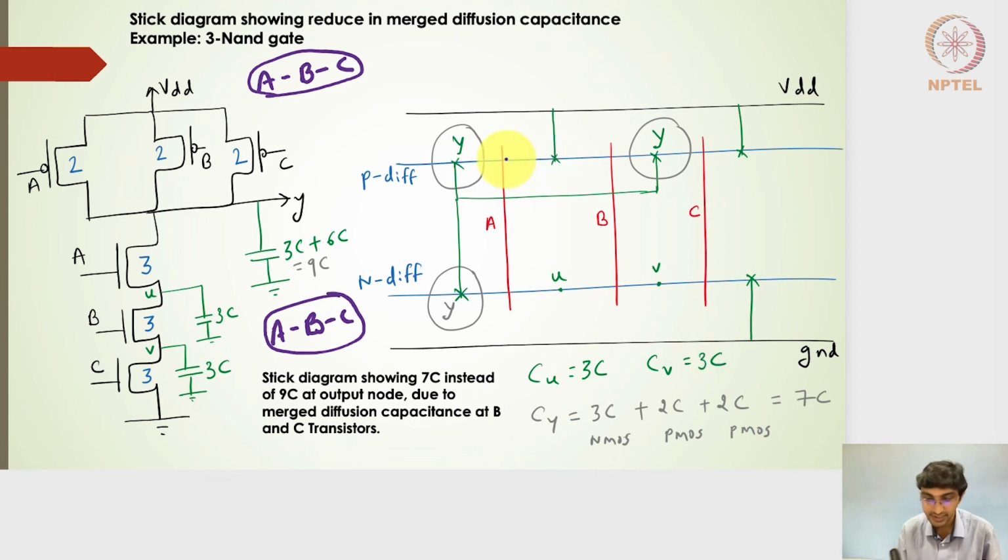On one side of the polysilicon gate, it is connected to the VDD, and both the B transistor and the A transistor are connected to the VDD. That means that for the A polysilicon and B polysilicon, I've connected the merged diffusion to the VDD.